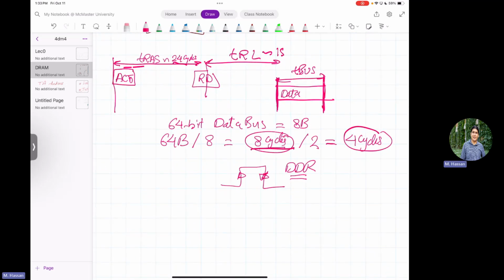And this clock of the DRAM is not the same clock as the CPU chip. Your CPU can be running at 1 gigahertz, 2 gigahertz, 3 gigahertz. With DDR4, we're talking about 2400 megahertz, which is 2.4 gigs. DDR3, the most commodity one, is 1.6 gig, I believe that's the highest speed you can run at. So it's another chip, and they can run at different speeds. And it's also the functionality of the memory controller, with clock domain crossings and these interesting digital design topics of how you transfer between two different clock domains.